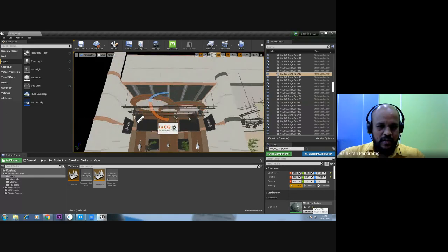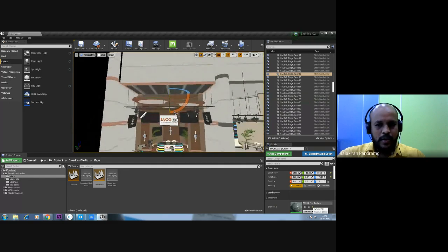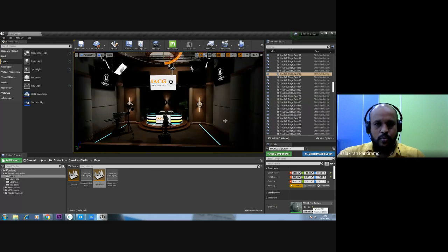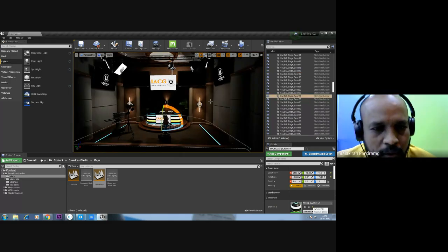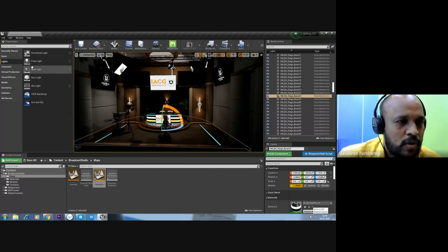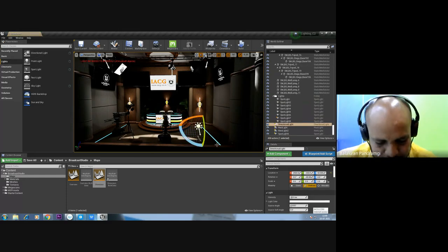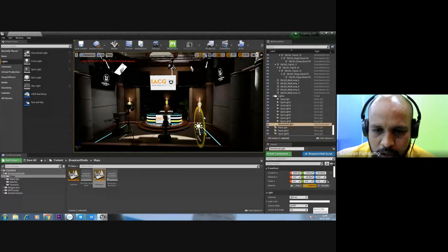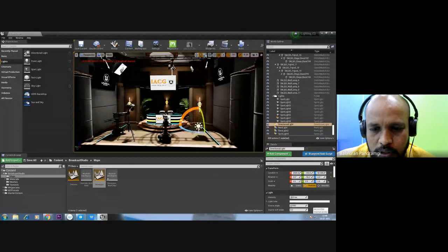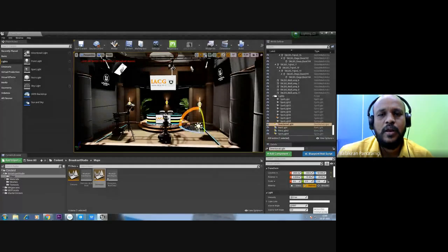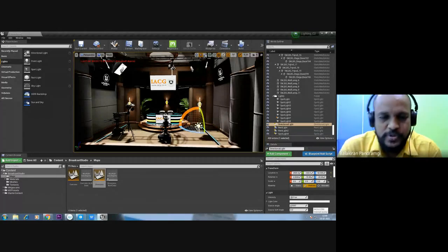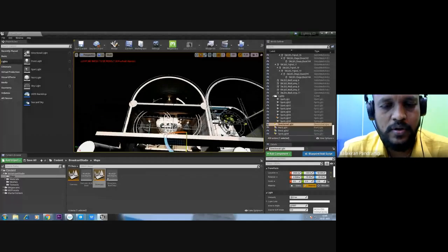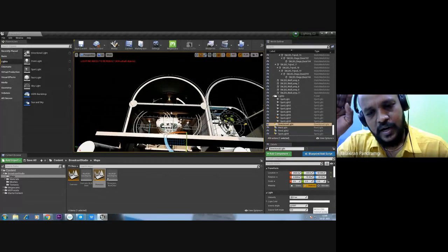But if I get a direction light right here, so right now my light is baked. Let me show you that. See, right now the lights are baked. This is the way my rendered scene will be seen. So see, if I get a direction light here, parts of it is getting lit. See if I move, the reason is the above object, whatever is there, the normals are reversed. It means only one sided it is there, so other side light will pass through.